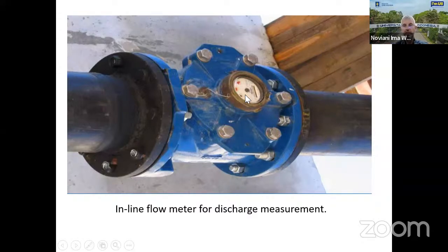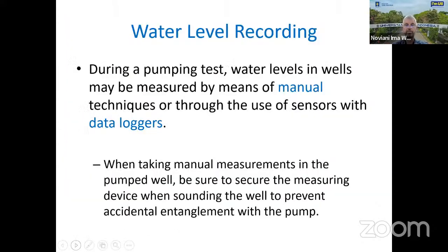One is for liters, for single liters. One is for tens of liters. One is for hundreds of liters. And then in this window here, you will see the cubic meters. So in other words, this little apparatus allows me to measure at any given time what is the Q, the flow rate. Remember Q from Darcy's Law, that's the flow rate. So we measure the flow, the Q, then we measure the water level.